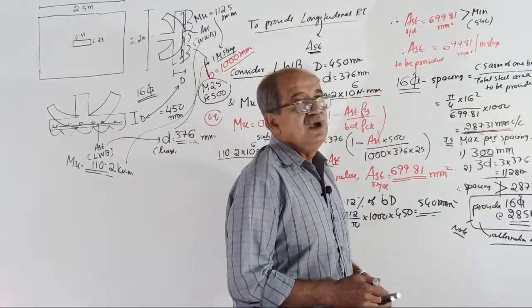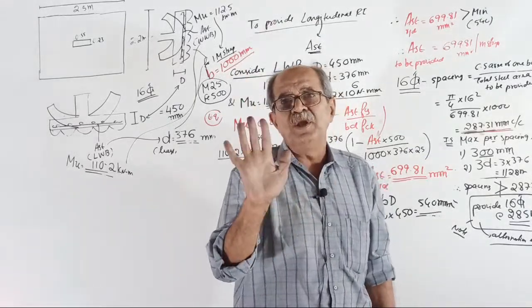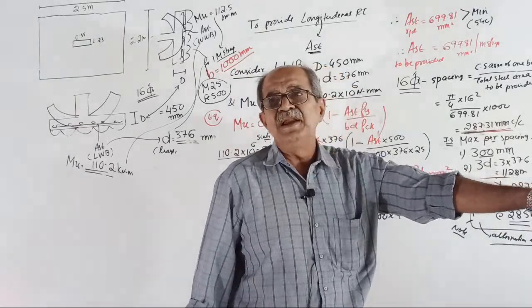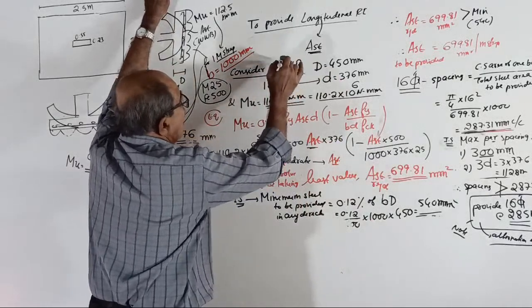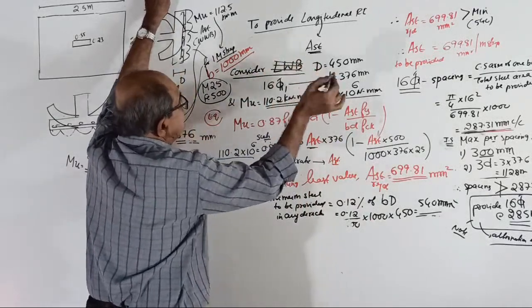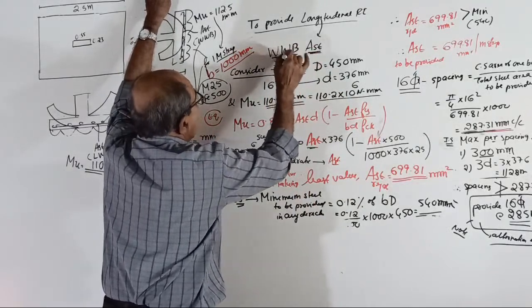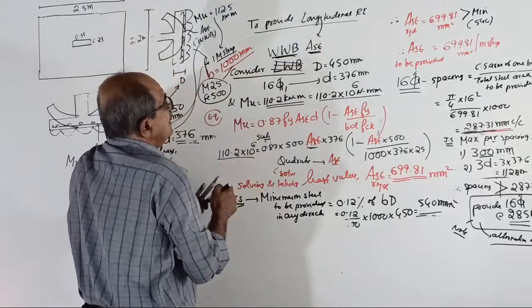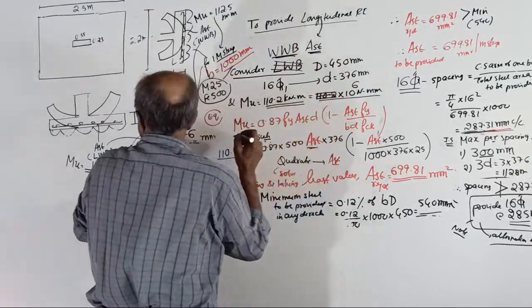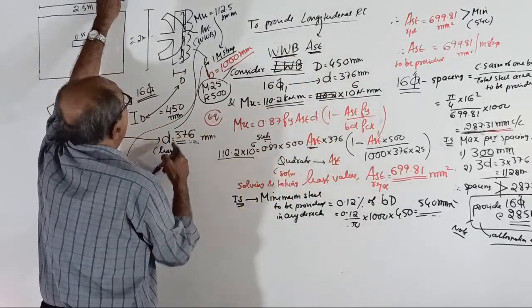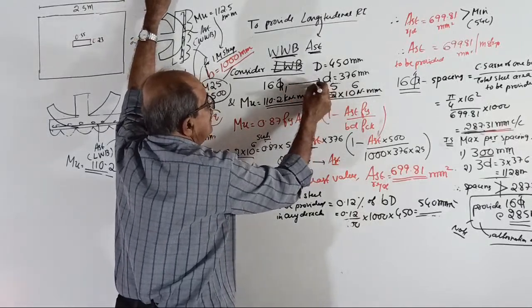Okay, now I completed lengthwise bending. The other, you have to do now. I am not doing it. I will sit there for 5 minutes. I will come here, start. Consider not lengthwise bending, don't cut it. Right, once again, consider widthwise bending. Once again do it. Start here. Once again come back here. Your D remains same, all remain same. Bending moment is not 110, it is 112.5. 112.5 is the bending moment.